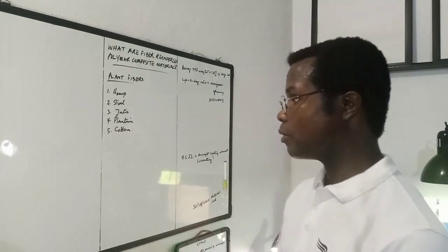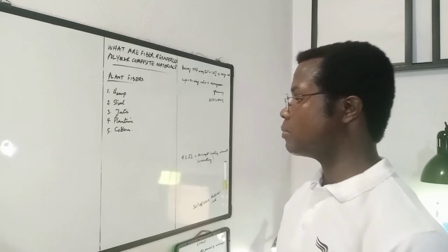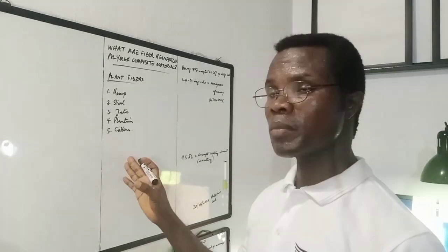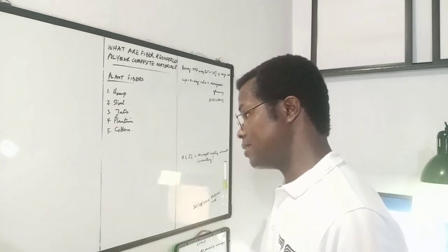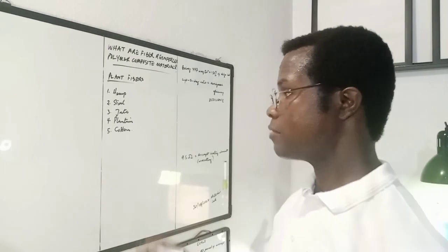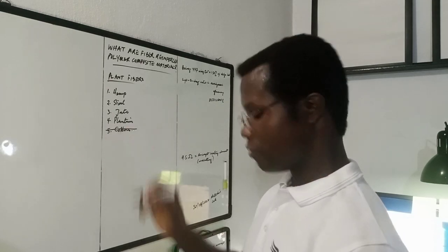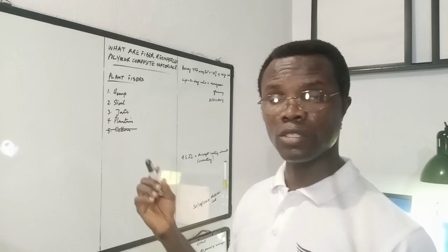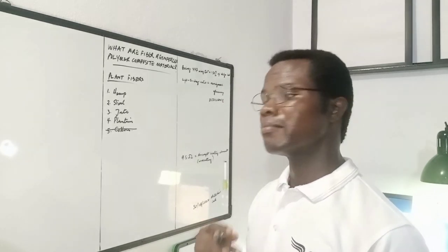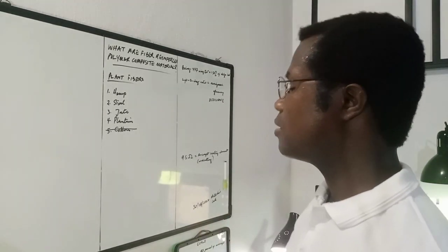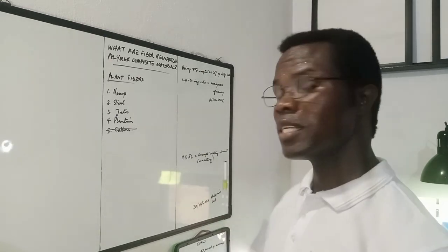Starting with cotton, cotton is a very important plant fiber, very high percentage of cellulose, extremely high. It's important economically for many reasons. Explosives, clothing, a whole lot of very important strategic material. But I'm going to rule it out of the list because its properties are not suitable in general for use in composites. The properties are insufficient mechanical strength. These are the fibers on the list, as well as many others.